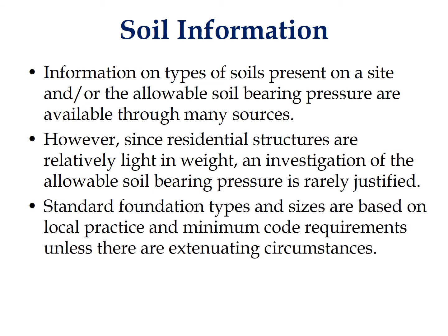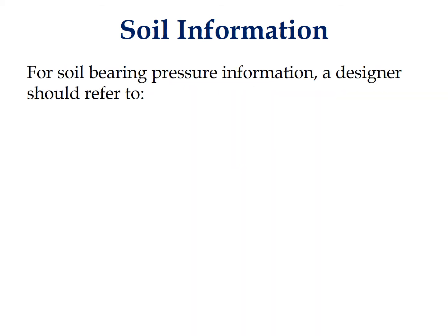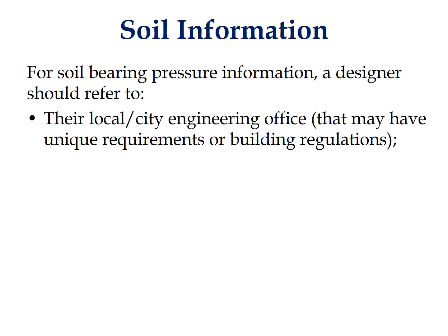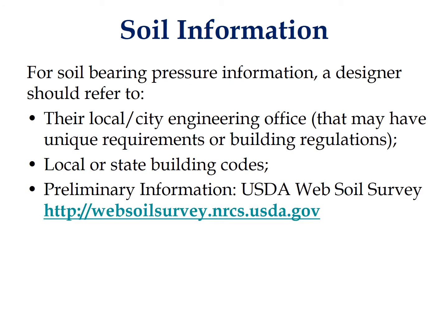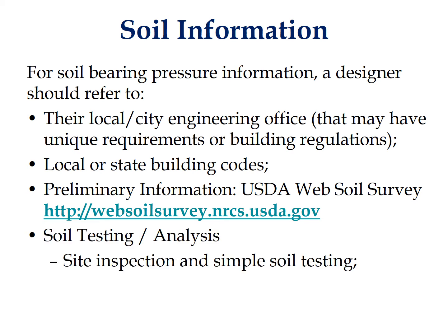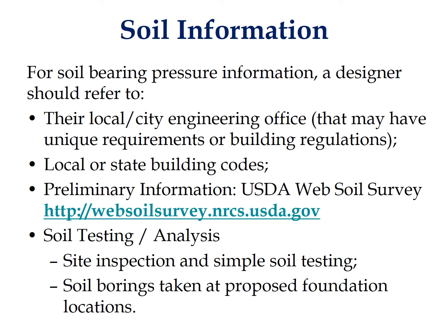Standard foundation types and sizes are based on local practice and minimum code requirements unless there are extenuating circumstances. For soil-bearing pressure information, a designer should refer to their local city engineering office. They may have unique requirements or building regulations that may need to be referred to: local or state building codes, preliminary information such as USDA Web Soil Survey, soil testing analysis, which includes site inspection and simple soil testing, and soil borings taken at proposed foundation locations.